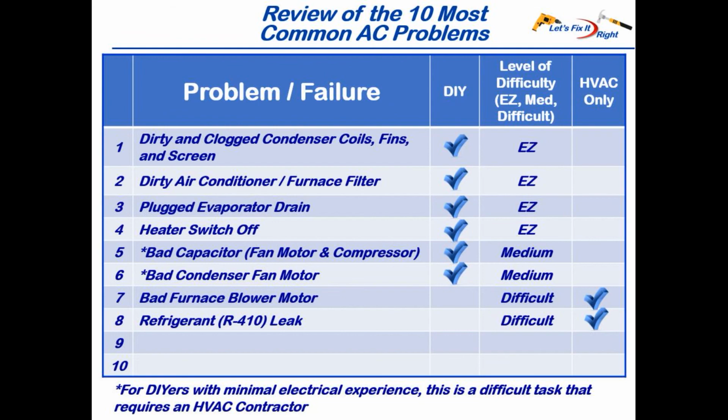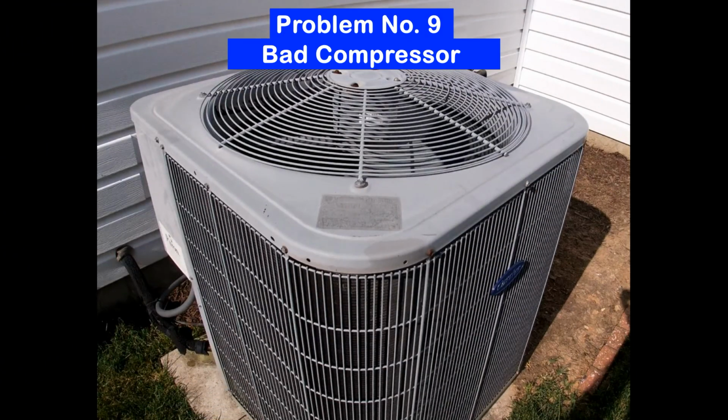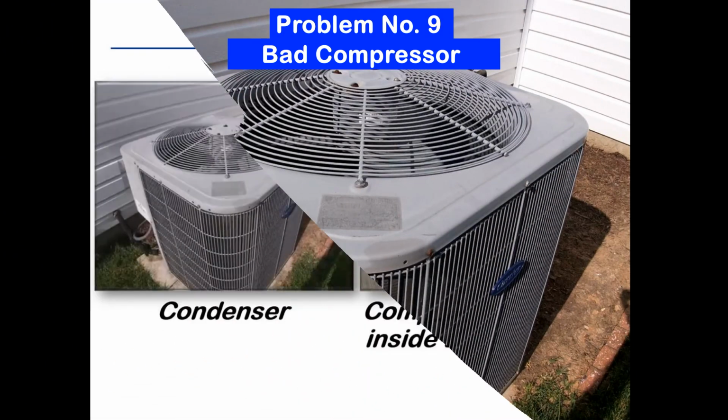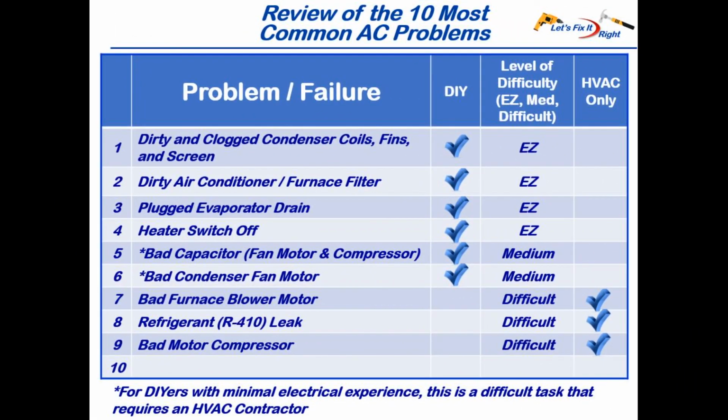If your outside condenser fan runs, but your motor compressor mounted inside your condenser will not run and possibly kicks the circuit breaker off, your compressor could be bad. Similar to an evaporator leak, a bad compressor is a major problem. In many cases, people opt to purchase a new air conditioning system altogether. Consequently, I'm rating this as a difficult task that requires an HVAC contractor. I also recommend that you get 2 or 3 quotes from different HVAC contractors because the repair or replacement of your system is going to be expensive.